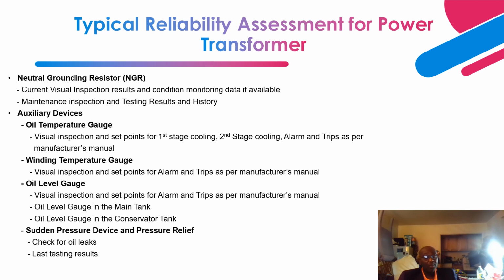If it is a lot, you also want to indicate that, because it helps with the planning piece, where you provide an indication to the maintenance crew to take note of it. If an outage opportunity comes by, they can take advantage of that and perform the cleaning of the dust that is located on this grounding resistor.